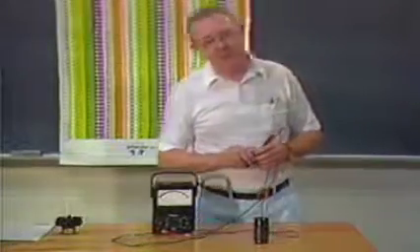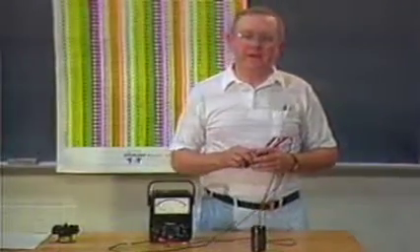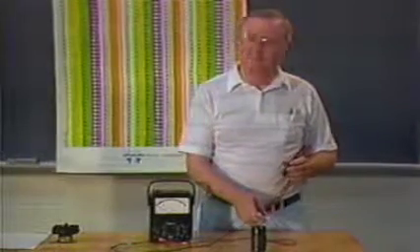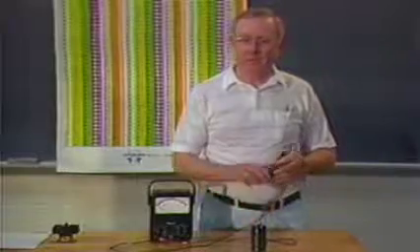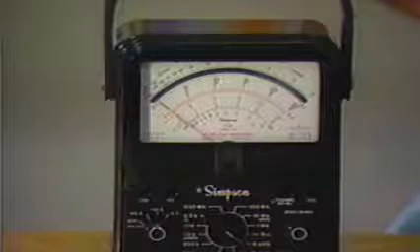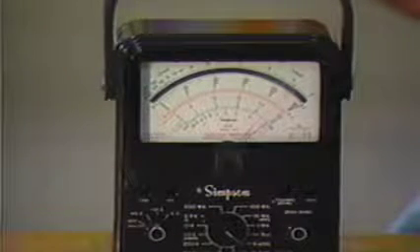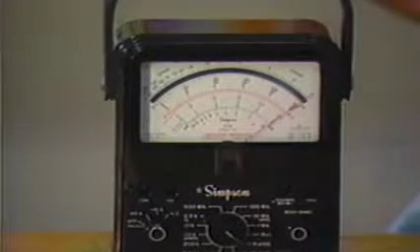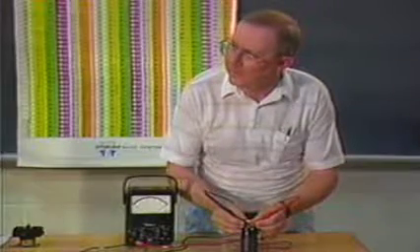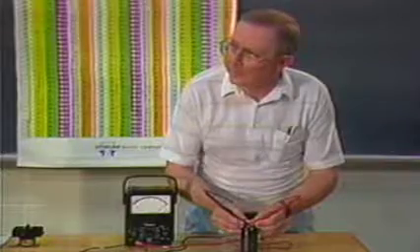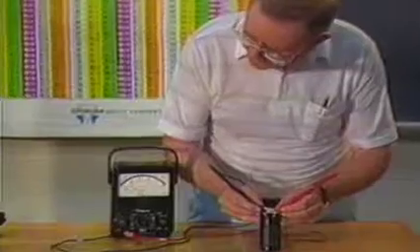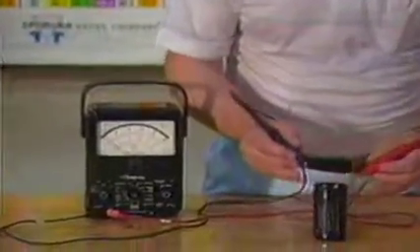Another problem that might occur with this capacitor is that it might have a complete short within from terminal to terminal. A dead short. If this were to be the case, when I touch the meter leads to the two terminals, this would be the reading that I would get. 0 ohms resistance. No measurable resistance, no rise and fall from the meter needle. That capacitor would be defective. The only time that the capacitor would be considered good is when you get a rise and fall from the meter needle.